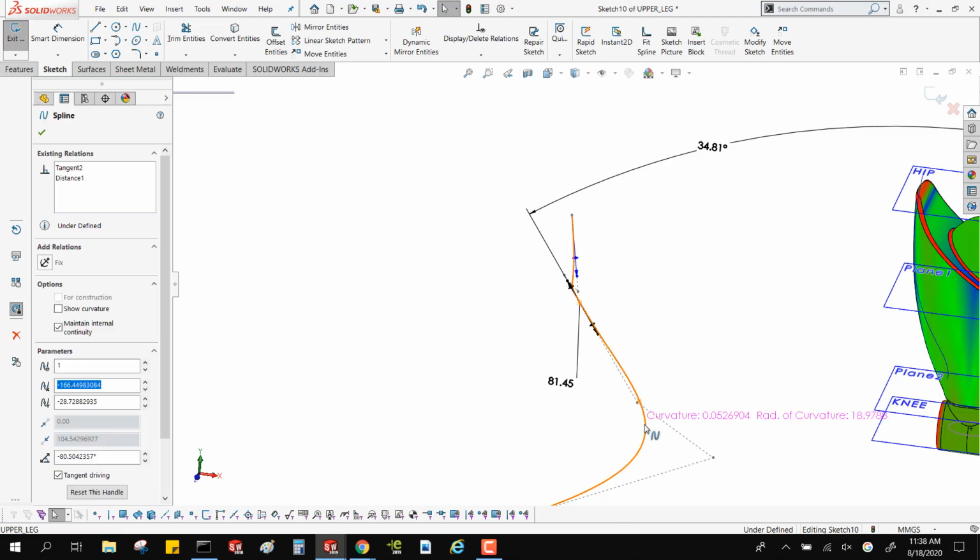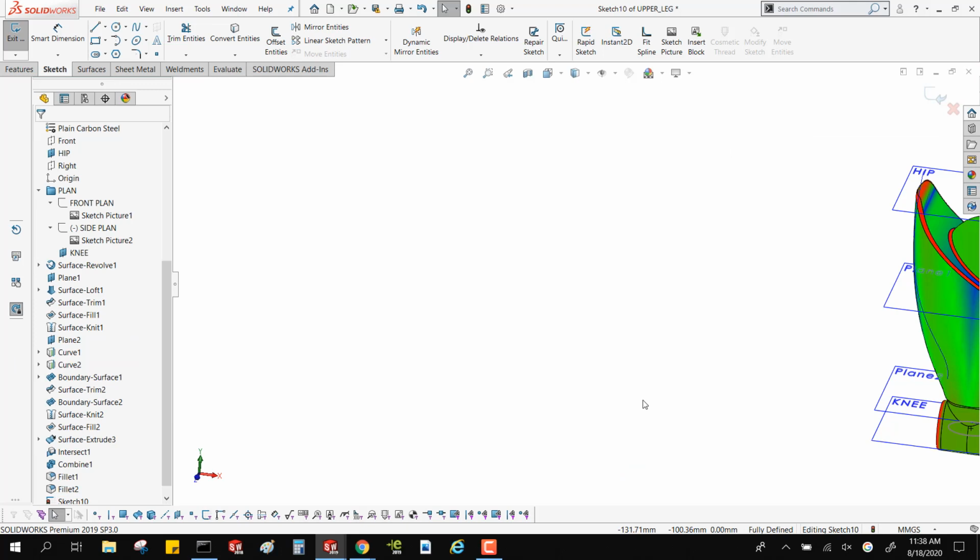Like I said, when I'm dealing with a machined part or a turned part, I definitely want everything to be black so that I know I have all the dimensions somebody's going to need to make it or inspect it. But when we're dealing with something like this, a loosey-goosey surface, and I want to be able to push and pull, and someone says, hey, can you make that corner tighter, or strange relative terms like that, if I've got all those splines locked down, I've got a lot of dimensions to go through, and it's just a horror fest.